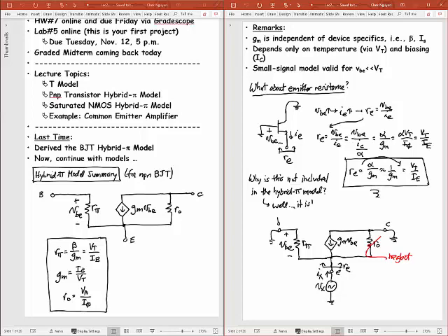But you see a resistor at the base, you see a resistor on the collector. You might ask, where is the resistor going up the emitter? Well, the resistor going up the emitter is represented in this by all of these elements right here. So we don't have to explicitly show a resistor at the emitter. All of these model that.